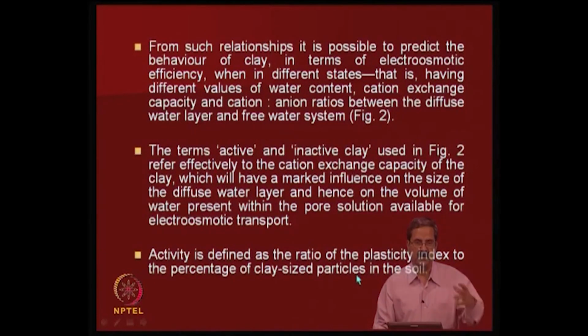So, PI is some number divided by the percentage of the clay particles, and that is what we define as activity. If the material is active, what does it mean? Activity is defined in terms of the negatively charged surfaces, and you can see that this activity and inactivity has a significant influence.